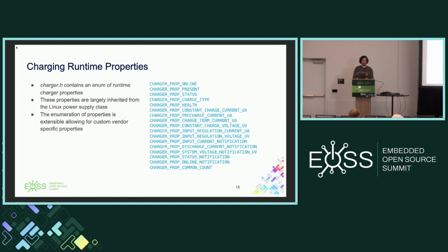And that property is used to call and grab the online value in an interrupt handler, so in the ISR, and then update the cached value. Because in that driver's implementation, when you grab a property, it's just the cached value. So once you get that interrupt, you actually go grab it through that notifier.